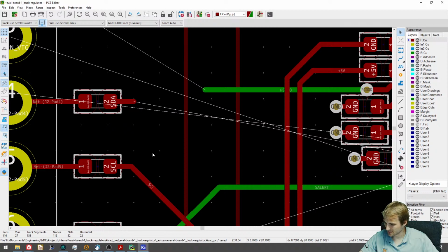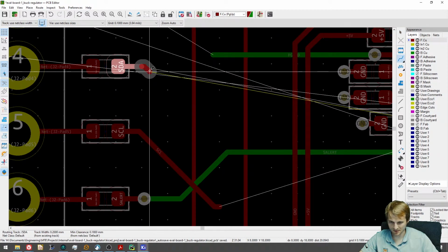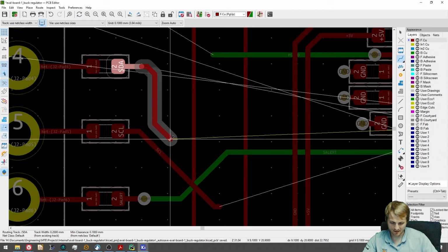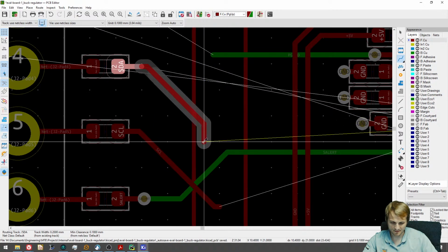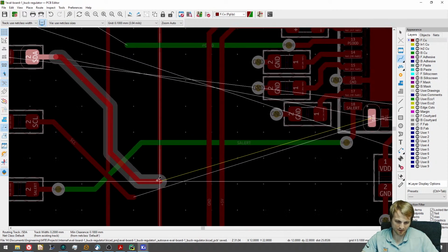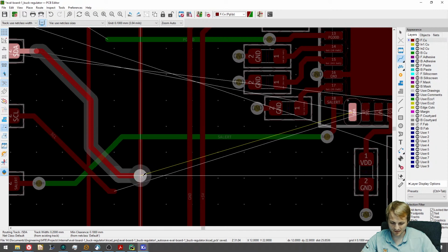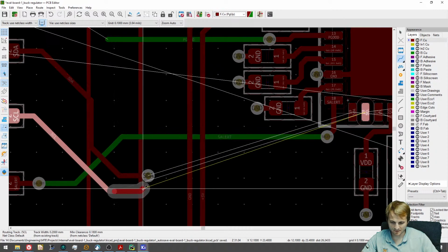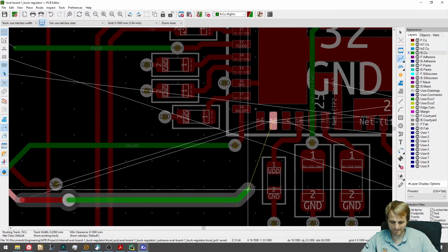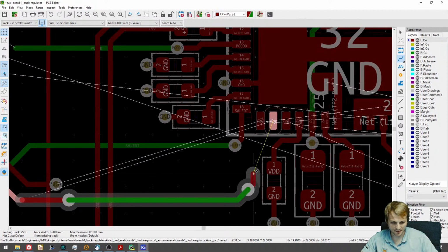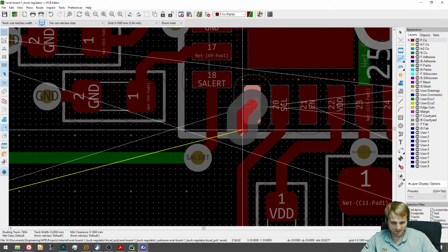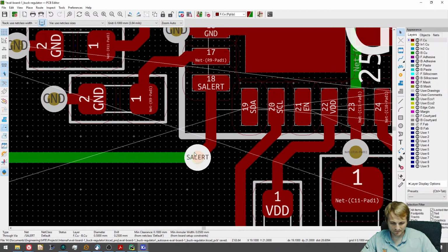Don't you put diodes after the input resistor? Yeah, you could totally do TVS diodes. And if this was a board that I was making production-wise, yes, we could. Normally on a board that I would be selling, or for a client, that would absolutely be what we would do. Anything that leaves the board should have them. I just never really thought to put them on here. And we're not going to have room here, are we? Nope.